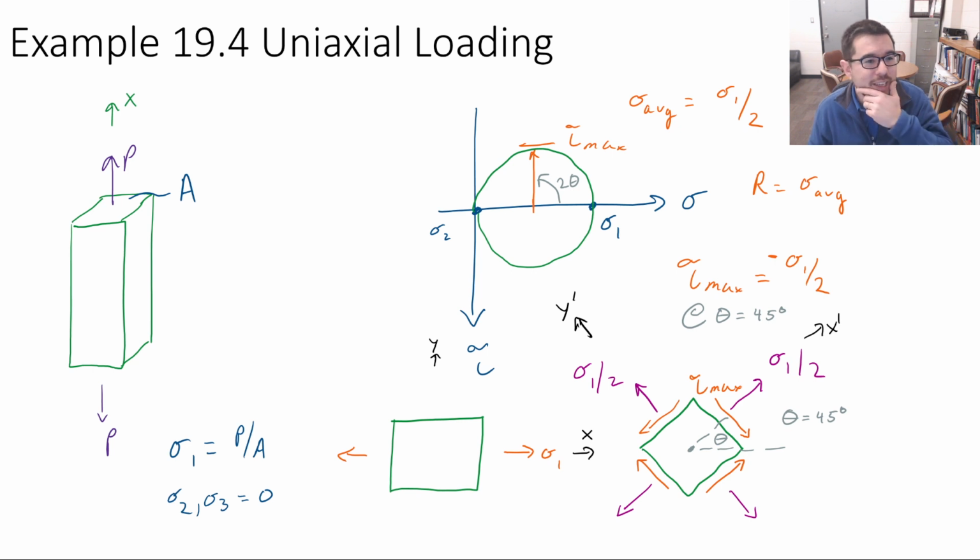But if that's the case and there's no shear here when we're looking at the principal stresses, which is the uniaxial case, what we normally do, it's like, wait, how could it fail? Well, it's because if we rotate the element 45 degrees, there is shear. This material is experiencing a shear stress. Failure might occur at a slight angle, at 45 degrees, for example, or there might be lines that form for a ductile material, because that's the direction the shear stress is highest.